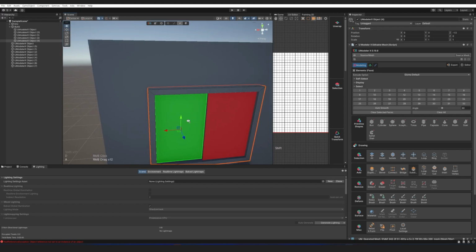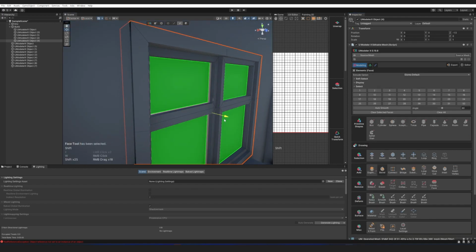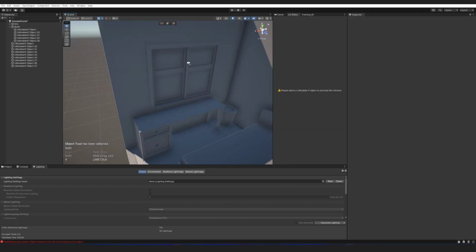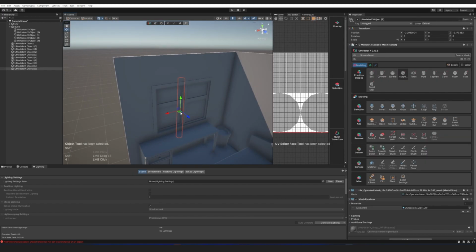Use Loop Cut to divide it in half and push one side further inward. After a horizontal loop cut, use Inset to create the window face. Push the created face inward to complete the glass window. Let's model the top part of the window.